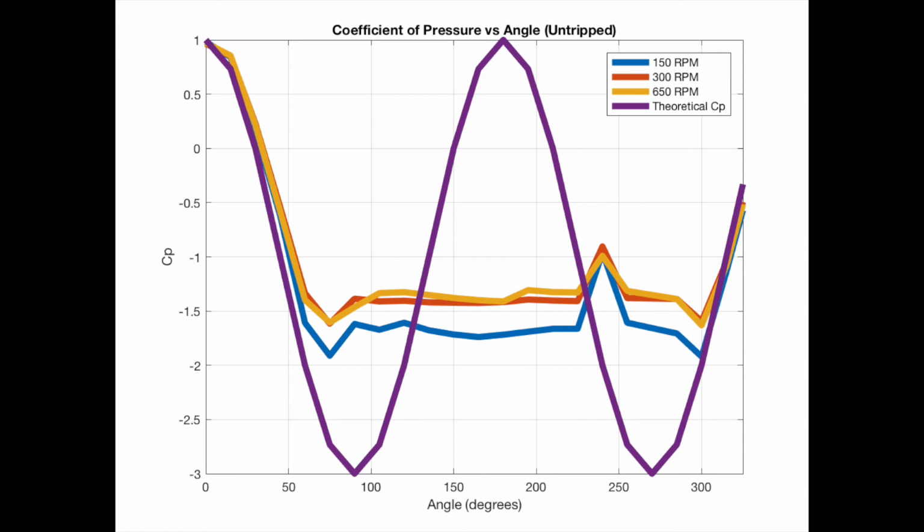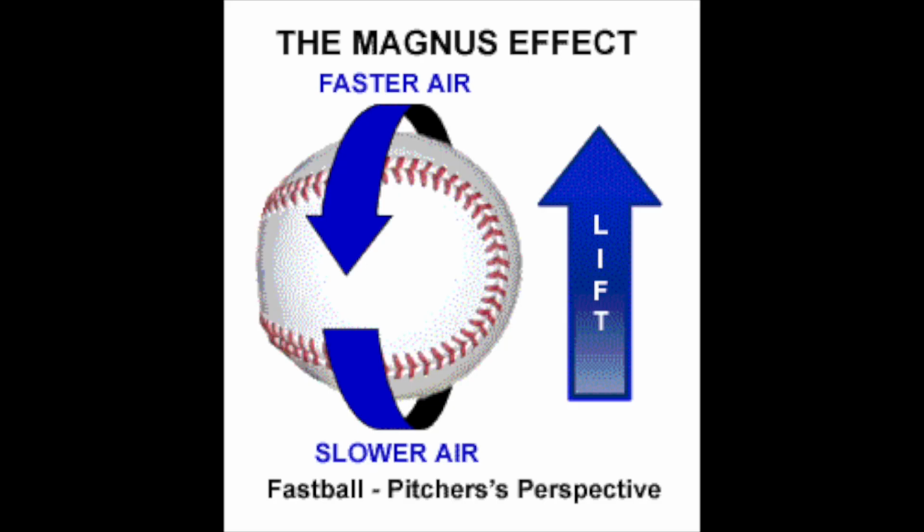If we had a ball instead of a cylinder in there, would the behavior be different with roughness, Reynolds number, asymmetry, etc.? Since the World Series is currently taking place, it would be fitting to use a baseball as an example. The stitches on a baseball give it a relatively rough surface. The stitches would disturb the boundary layer, like the trip strips on the cylinder, moving the boundary layer further along the baseball's surface, decreasing the size of the wake in the process.